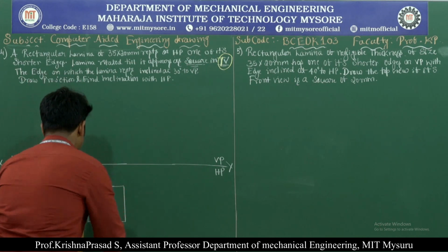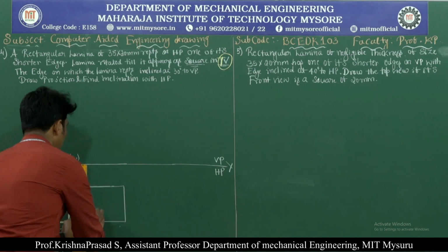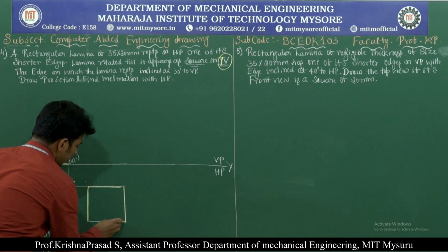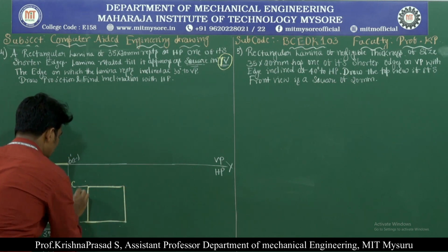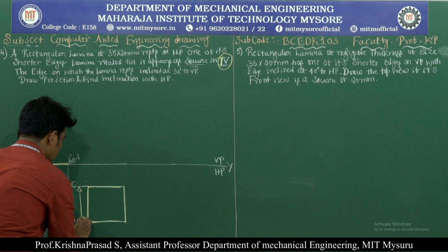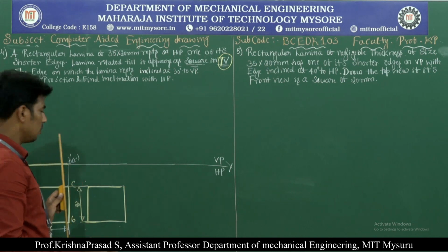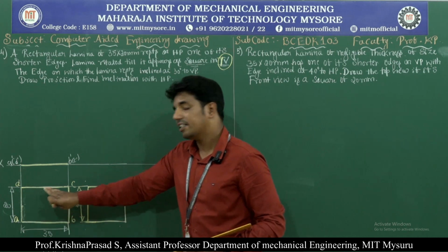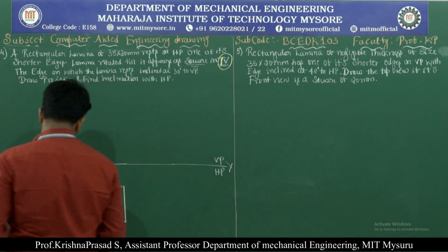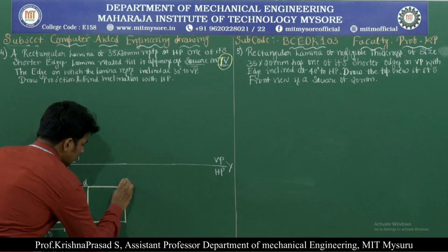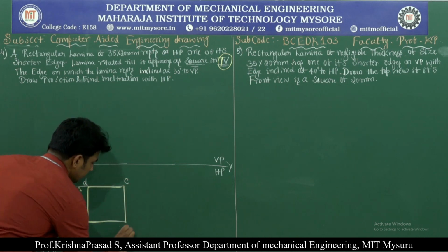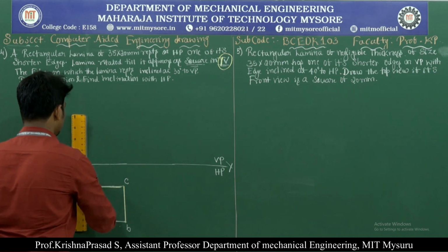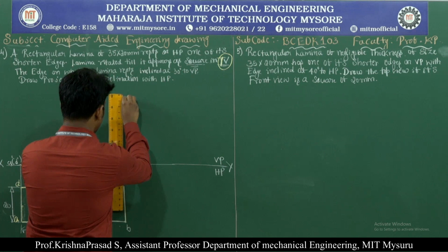Okay, now we have completed the dimension of the square lamina with 20 mm. This is called the square lamina. It appears in the top view. Now we need to keep the same naming as in the front view. That means this is called D, this is called C, this is called A, and this is called B. Next, project the two straight lines into the front view.